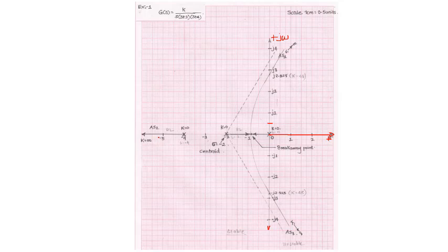Next, after that, identify the poles. So how to identify? Here we are going to identify the poles. This is the first pole. Mark it at S is equal to 0, and here write S is equal to 0. At this particular point the branch is going to start, so write K equal to 0 there. Then on the negative part we have minus 1, minus 2, minus 3, minus 4, minus 5, going on like this toward infinity.